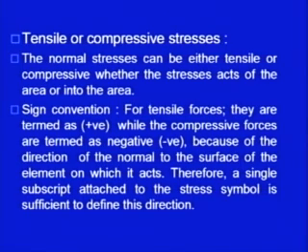So if we are just doing the axial pulling, then these are the tensile stresses. If there is an axial compression, the lines of action are at both sides of the object through one axis, and the compression is there, we can say these are the compressive stresses. The sign convention: if in a normal stress we are doing the axial pulling, these are the tensile forces, and they are termed as positive. Or if we are applying the compressive forces through the line of action of the central axis, we can say these are the compressive forces and they are termed as negative.